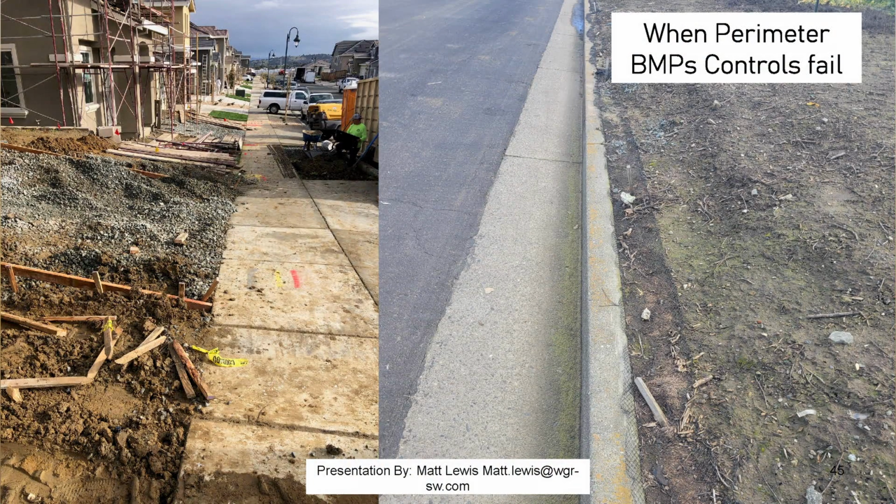Or on the left, this always happens, the guy in the little yellow shirt, he was part of the landscaping crew. So this is a site that is getting pretty close to being done, and the landscapers hate fiber roll. It's the bane of their existence. And so they will come in and remove the fiber roll. Usually it's piled up in the street, covered in sediment, right next to a storm drain. So what I was trying to tell these guys, okay, if you want to get rid of the fiber roll, put in a curb cutback because you have your sidewalk there.